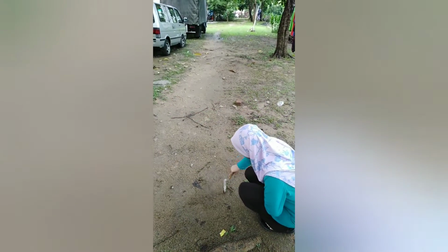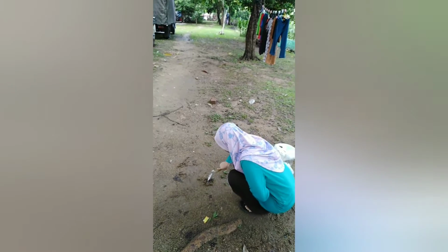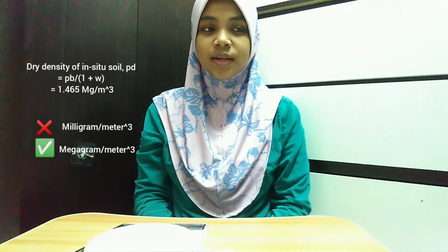Search for a suitable spot and excavate the soil using a trowel to the required depth. Place the sand pouring cylinder centrally over the excavated hole. We can calculate the bulk density of the in-situ soil and the water content of the soil removed from the hole by using the data obtained from the experiment. Finally, by using these two data, we can calculate the dry density of in-situ soil, which is 1.465 Mg per